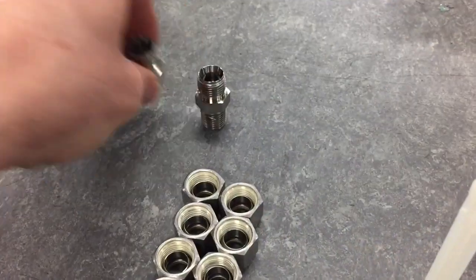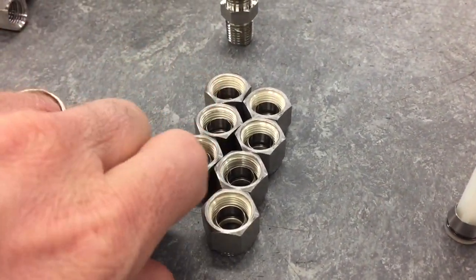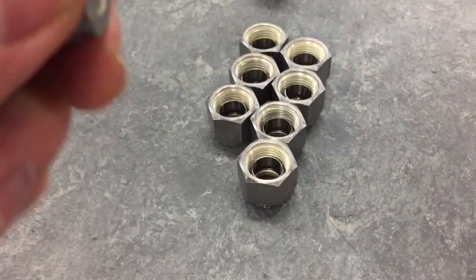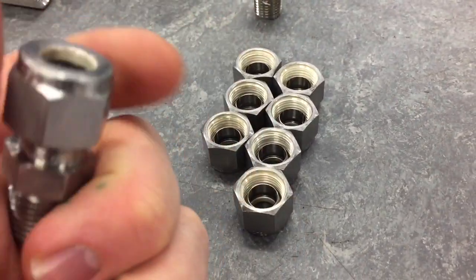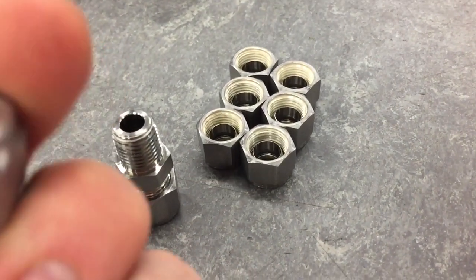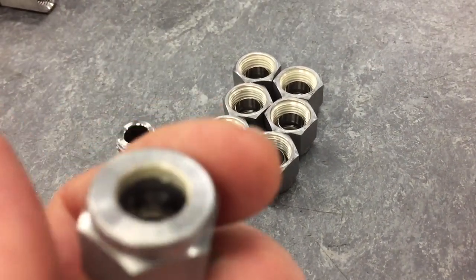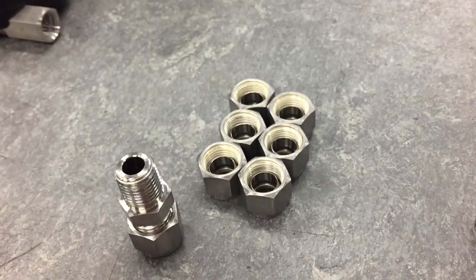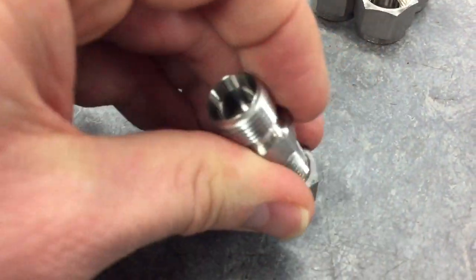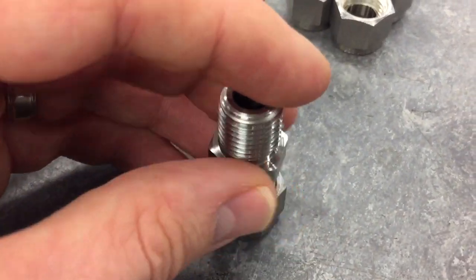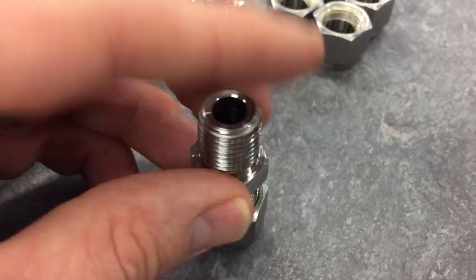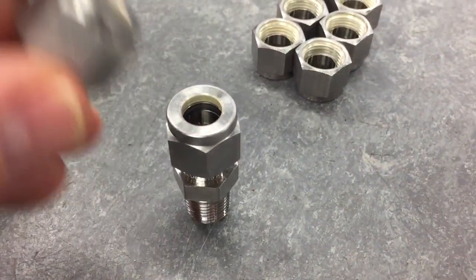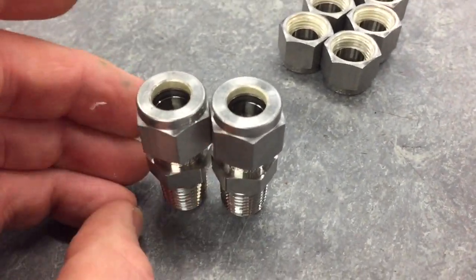So the next part, we want to place these fittings onto a nut here. So I'm just going to go ahead and put them on for both of these as well. And so if I just thread this on, I'm using one hand. Let's turn this upside down again. Oops, I've got it the wrong way, that's why. There we go. So now we have nut and ferrule installed on both of these fittings.